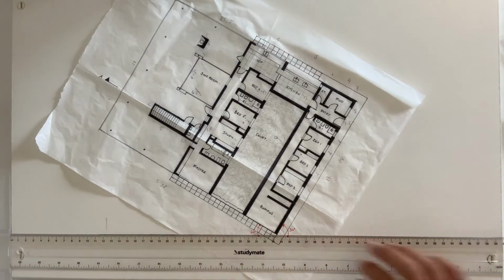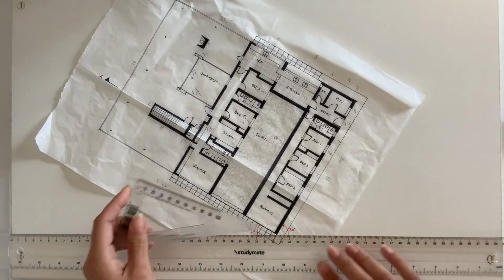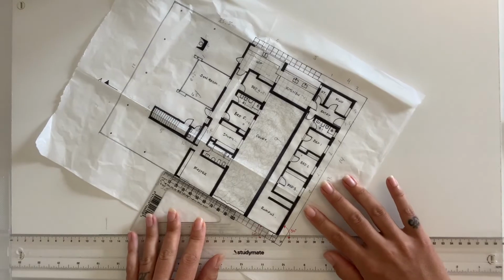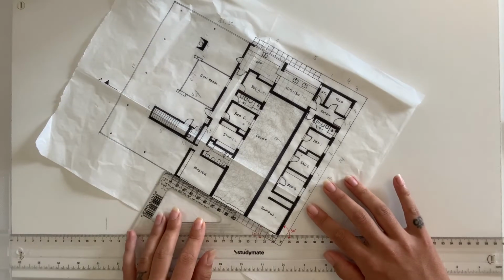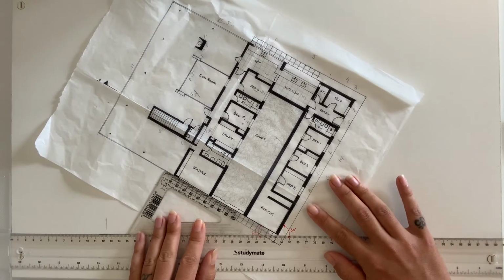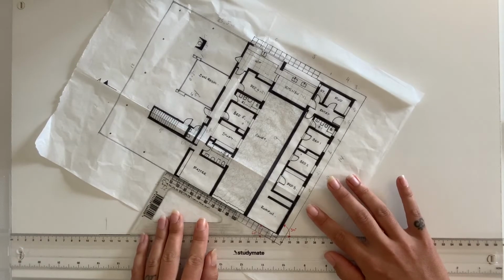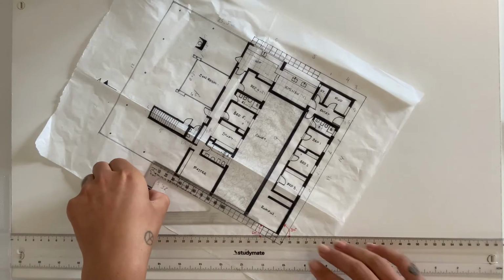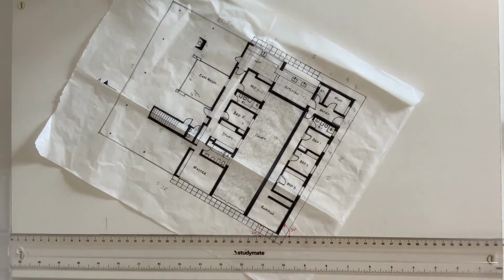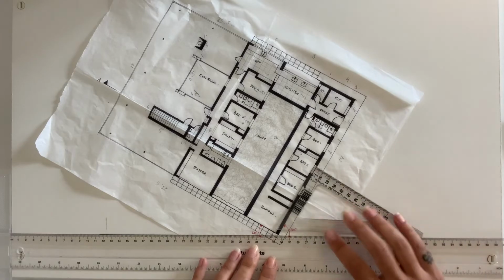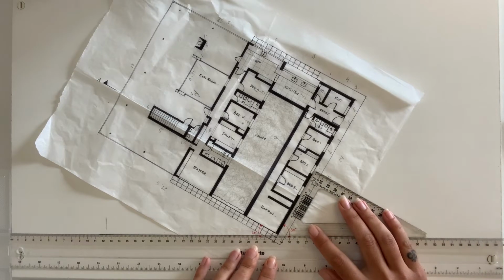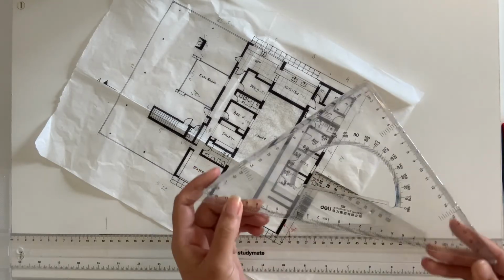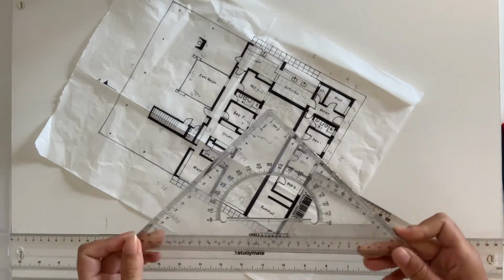Once you have a reference line, then you'll line up the corner of your floor plan and you'll check with the ruler. This is a 30 by 60 ruler, and you just lock it with the T-square to check the walls are at the correct angle on both sides. So this ruler has the longer side and the shorter side. In contrast, you've got the 45 by 45 ruler. This has got the right angle, and